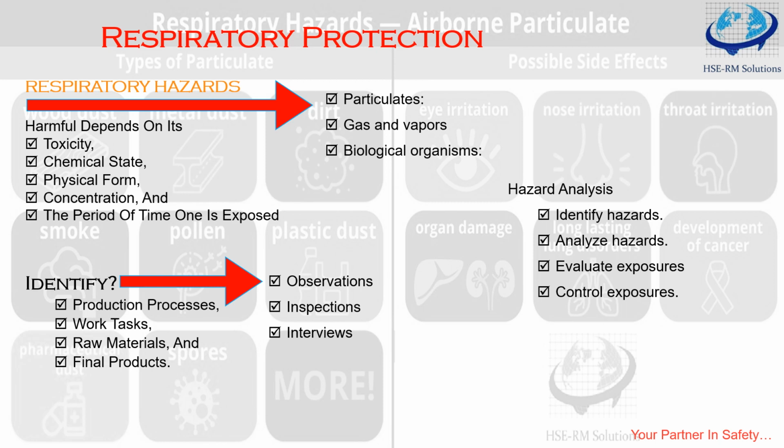Normal air concentration, oxygen concentration is 20.8% by volume. When the concentration drops below 19.5%, the air is oxygen deficient and considered immediately dangerous to life and health. That is IDLH. Remember this term.